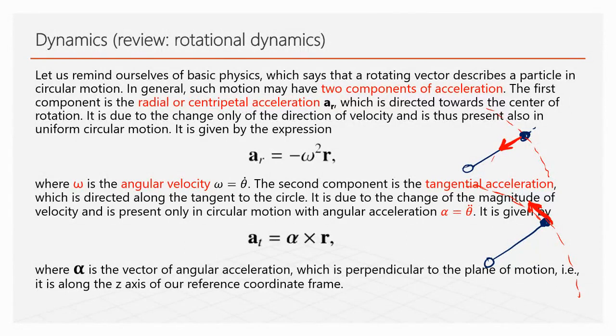That's why motorbikers, when they want to turn, have to push and apply some force to make their bike bend, because they want to change the direction of that rotation vector. We don't have that in linear movement. In linear movement, if something is moving, we don't expect anything like this, but in rotation, there are other components we need to consider.